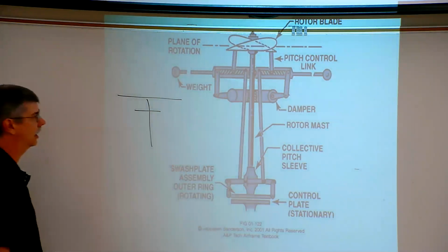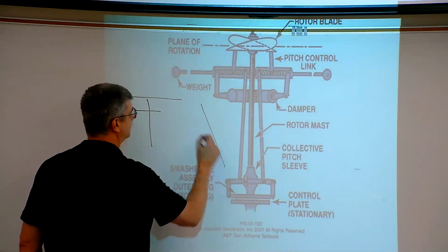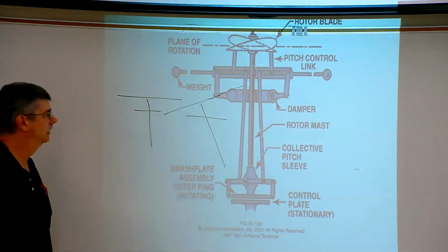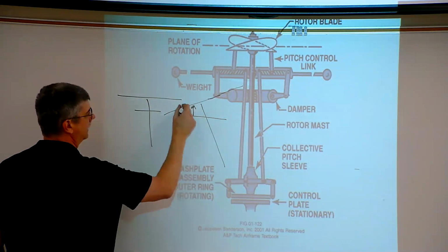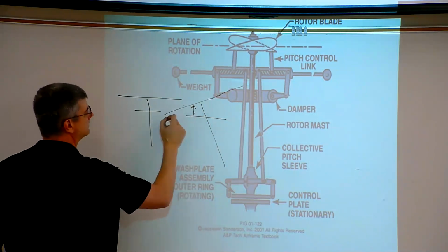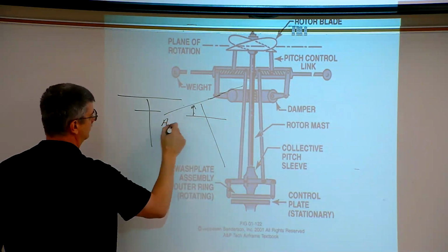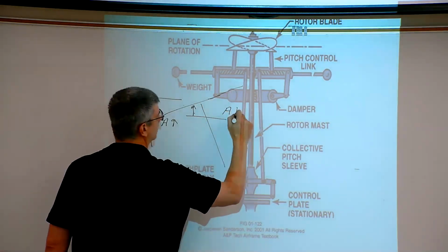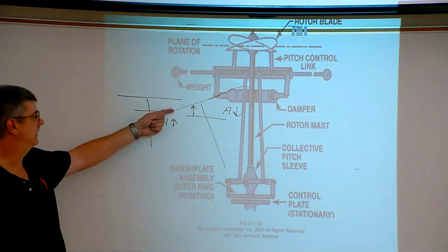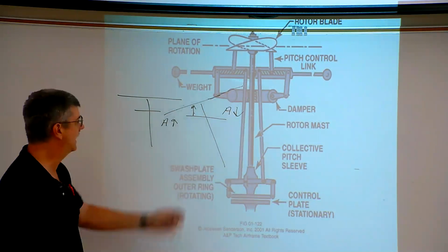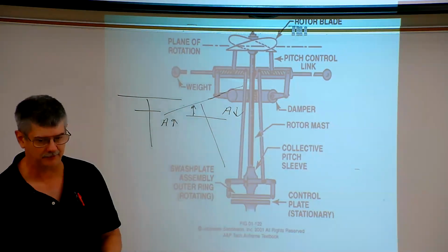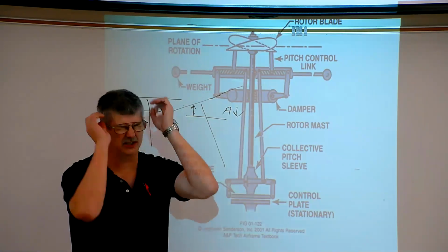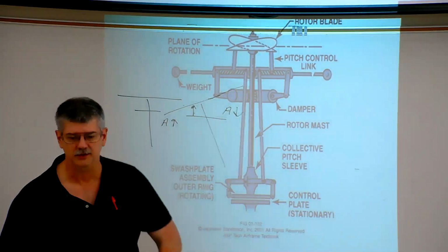And there's the bell bar. If the helicopter tries to tilt over, the bell bar stays horizontal. The link rod then here, because the blade got closer, this blade, the angle will increase. This one, the angle or the pitch will decrease. So aerodynamically, this side will create more lift than that side, uprighting the helicopter. Please let me know if you just get the concept slightly.